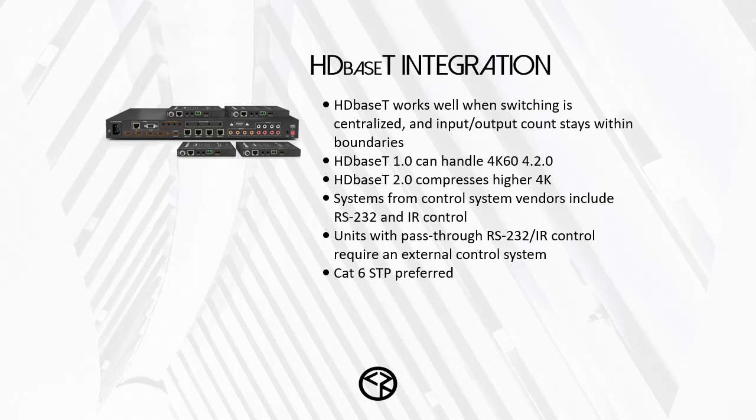In addition, you would generally use Cat6 shielded twisted pairs, mainly because it's all a 10 gig system, so they recommend you don't run the cables next to each other in a bundle for the next 20 meters, and you try to keep everything random. In most cases, Cat5e or Cat6 cable can work. However, they have a lot of restrictions on how you run the wires with UTP cable. You don't want those cables run as a bundle together because noise can definitely be a factor, because again, you're using PAM16, so there's a lot more things that can come in.